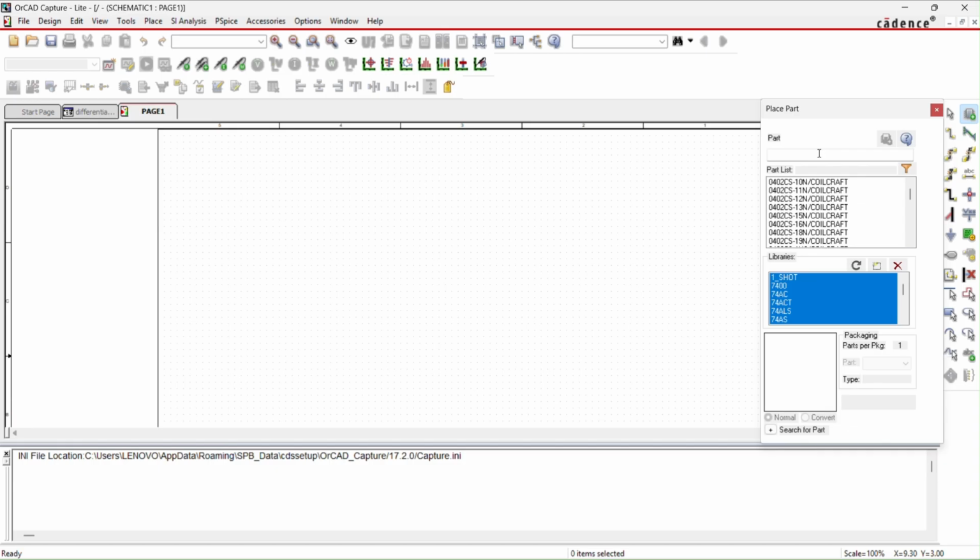So now I'm going to do the differentiator circuit. For that you need the resistor and the capacitor. Resistor and capacitor belong to the analog library. There are other resistor capacitors also, but some may not work. So take it from the analog library itself. So just type R. So R bar analog. Analog is the library, R is the part name.